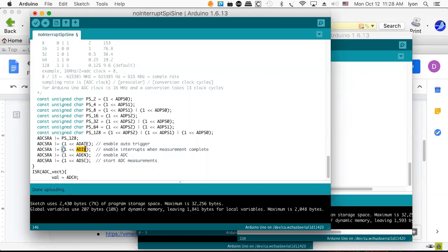So you have to be really thoughtful about how you mask interrupts, because otherwise you're going to miss perhaps important events. But having a human being turn a diddle pot is not that urgent an event as opposed to outputting to the DAC, which is a higher priority item. So you really have to think about why you want to have the interrupts turned off.